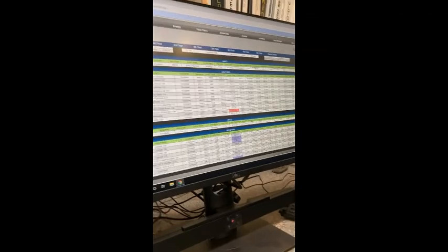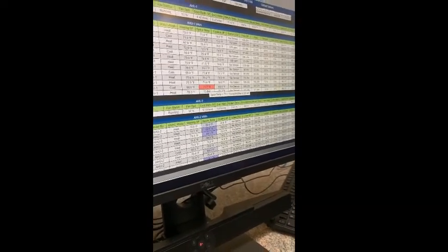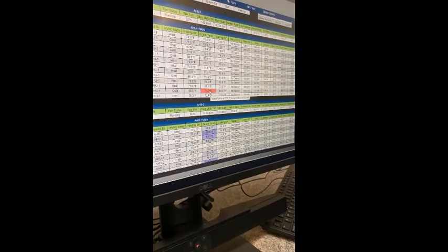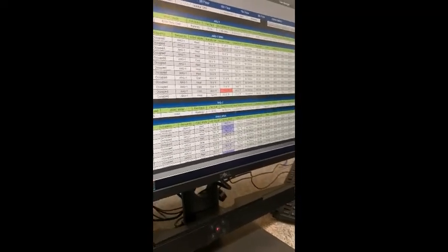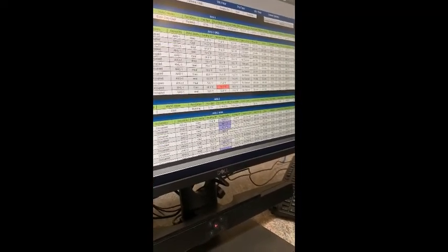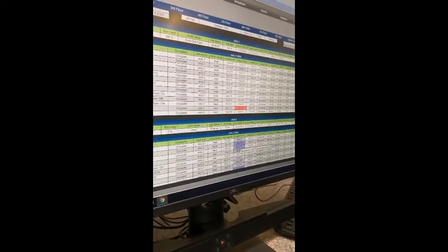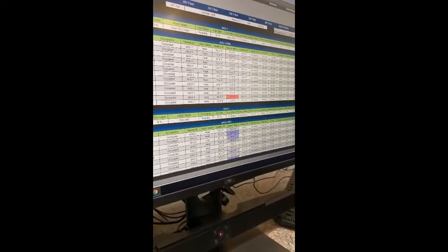If you look here for space temperature, you can see that this room right here has turned a reddish color. That's to indicate to you as a user that the temperature is above the set point. It may not be an alarm, but it's just turned slightly redder, and it'll go a deeper red or lighter to clear, based off how far above set point it is. Down here we can see some of these where you can see different shades of a bluish tint to the space temperature to show you that these are slightly below set point temperature.